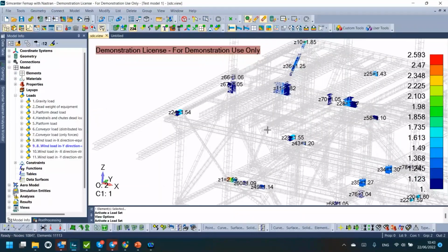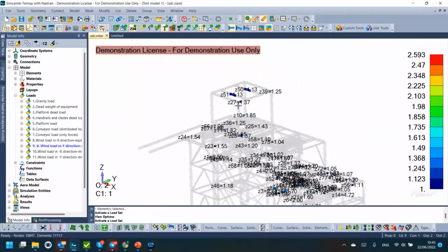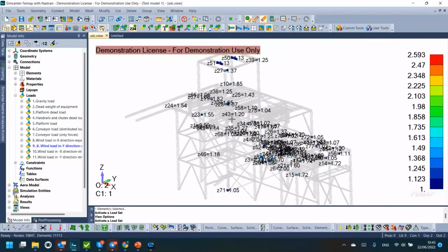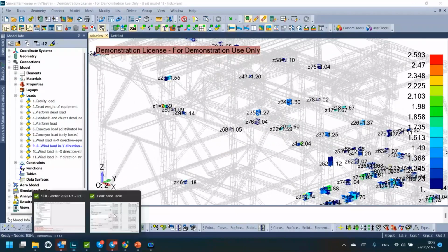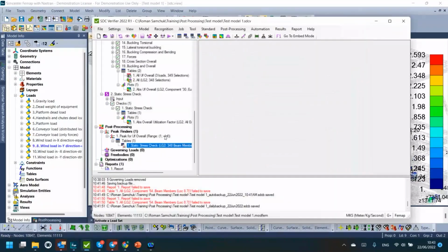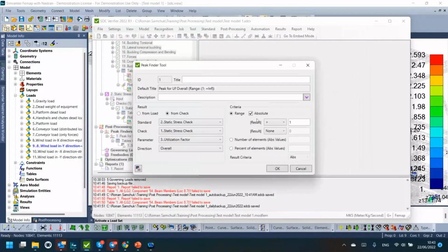This is much better. So basically, what we've got is one complete picture which highlights separately all zones with the utilization factor higher than 1. But this is some criteria which we prescribed at the beginning, and this is easily adjustable, because somebody of you might say, okay, but I don't care about this utilization factor higher than 1. I want to get everything which is higher than 0.5 and less than 0.8. Yeah, it is also possible, because you can set up the range of these values.